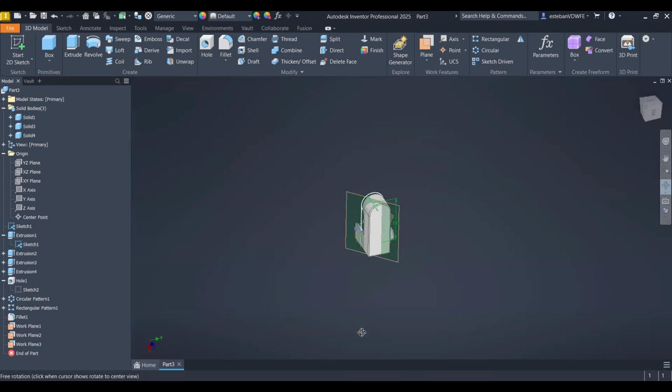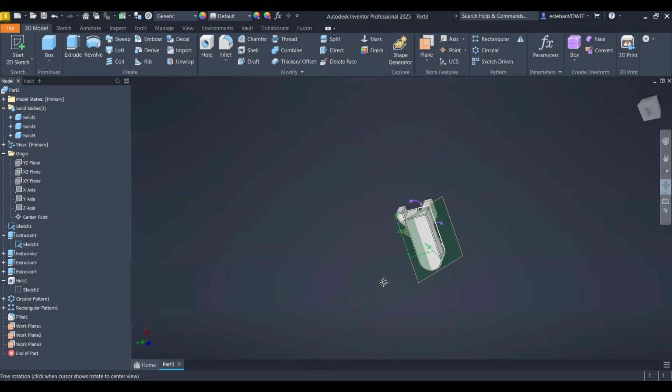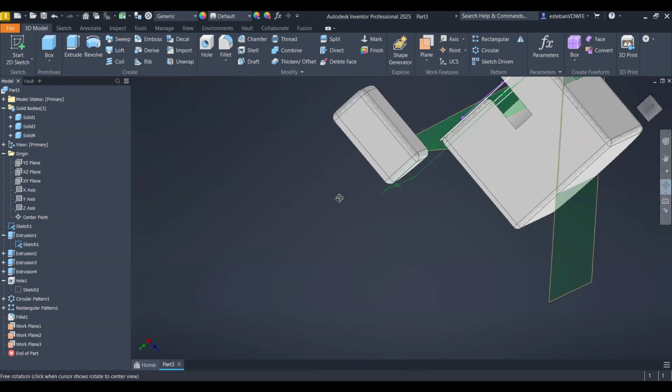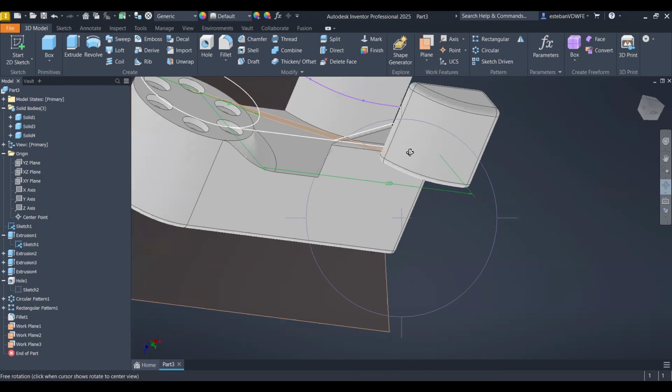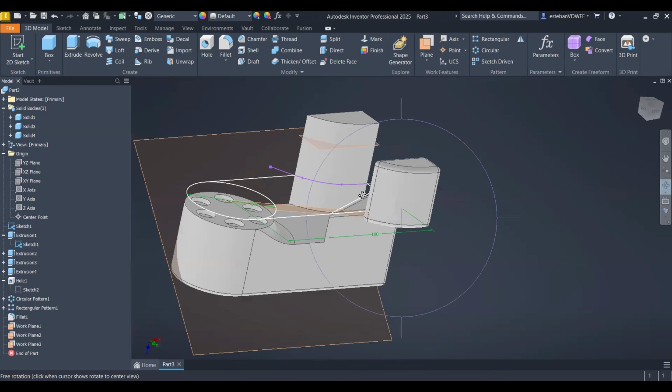But which center? Okay, well, in here, for example, I lost my center, the original one, so it's moving kind of weird. What I need to do is to just click on the element that I want to become the center. For example, I will select this one. Now everything rotates around it. And you can scroll in and you can click again on the element that you want to be at the center of your rotation point.